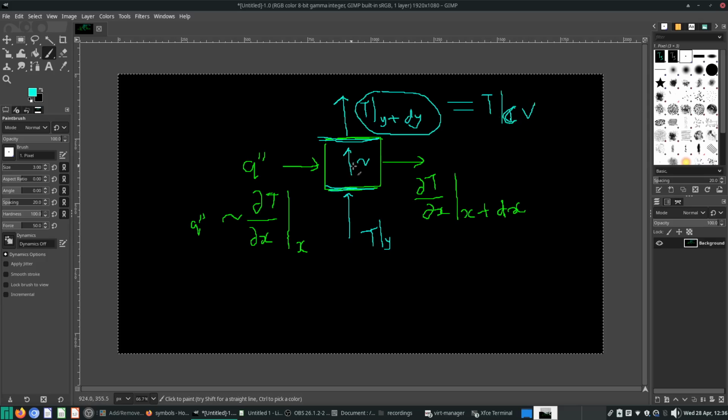We assume the control volume here has just one uniform temperature. That's how we can think of it differentially speaking. This thing here will be cooler. It will not be the same as the control volume temperature, but likely it will be cooler. It will be some function of y or whatever. Why is it cooler?